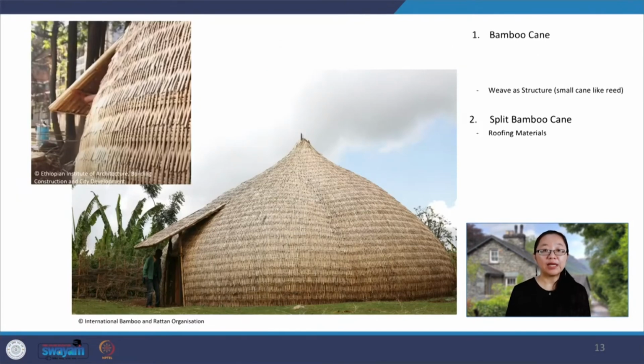Besides the bigger bamboo canes like the examples mentioned before, the small ones are also used as structures, like the ones used in Sidama vernacular house in Ethiopia. The house is a beautiful onion-shaped dome. It is constructed with a triple layer of bamboo canes split in half, bamboo strips, and ropes for structural support. Bamboo strips are longitudinal segments of the cane. They are obtained by making cuts parallel to the fibers.